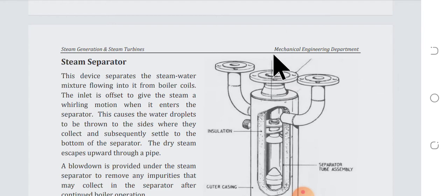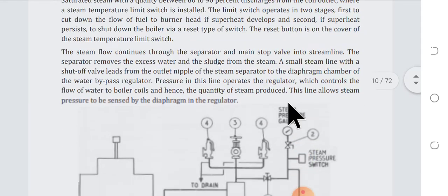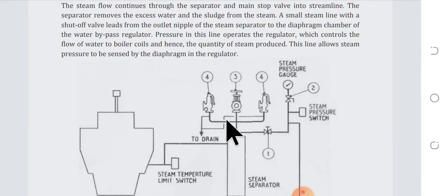This is the exhaust of the boiler, and parallel to this we have two pipes, with the exhaust pipe for the safety valve. This is the safety valve. And you see that there is no valve connected with the safety valve, because it is a fundamental law that on the safety valve we don't install any control valve or any stop valve. If someone intentionally closes the valve and the boiler temperature rises, it can explode.